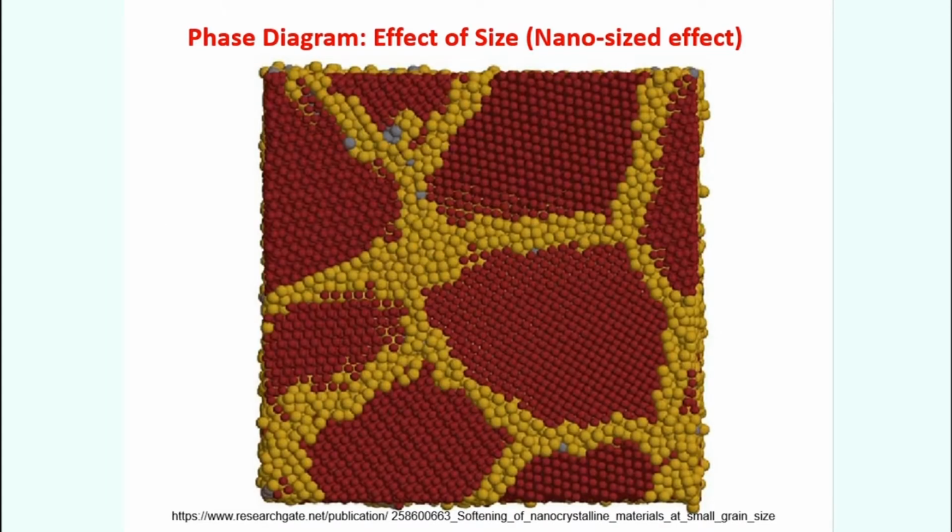So, this is what I have shown you. The grain boundary structure is completely different from the grains. In the grains you have a well arrangement of atoms, grain boundaries will have different atoms. Okay. Well, that is something which has been discussed from the days of Herbert Gleiter long back, 1980s to now, and people have really converged that this kind of structures are possible in nanocrystalline materials.